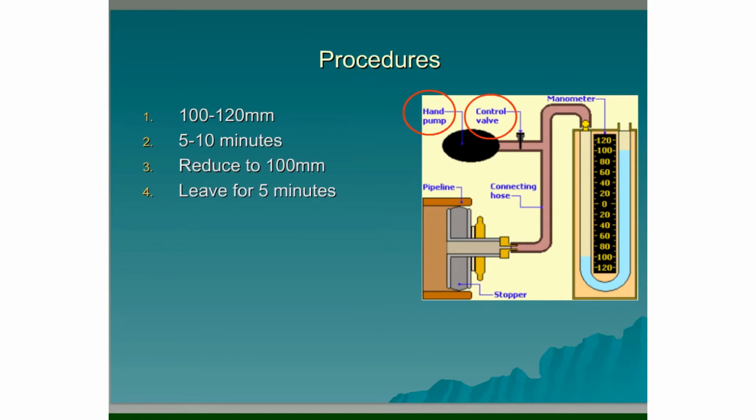We leave this for a further 5 minutes, and the pressure should not drop below 75 millimeters. If it does drop below 75 millimeters, then the system has failed the test.